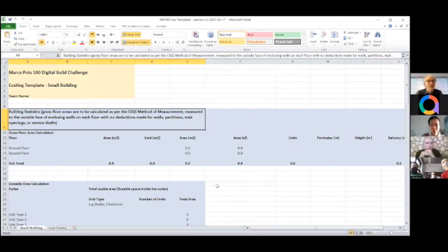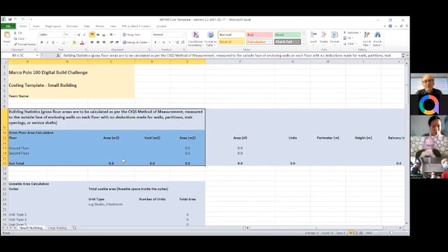And what it's doing here is laying out the areas in quantities, and at the start, the basic floor areas that you're proposing and how to measure them. In this area, from, say, line 9 to 16, we're talking about the total floor area. So if you had a tape measure and you could hold it on the outside of the outside walls and run through the thickness of the walls to the opposite walls, those are the measurements we want